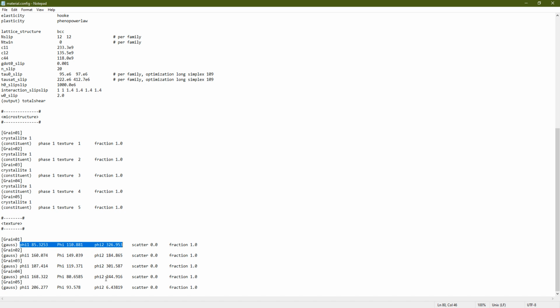Which means this is a single phase material with 5 different grains. Each grain has a different orientation, and that orientation is defined here. And now we want to see information about phase, right? They all have a single phase, which means it is just one material, which basically means it will have the same crystal structure, the same number of slip systems, the same critical shear stress, and so on, and hardening rule and so on. What will only change is how, when we apply the total force, it is resolved on each plane. Maybe for the same material, because it is resolved better, this slip system will activate and the other one will not, right? And this is what crystal plasticity is.